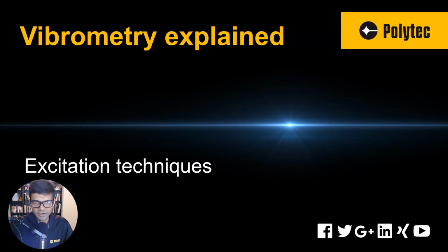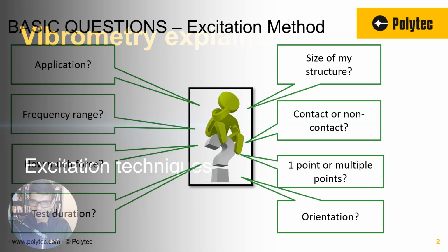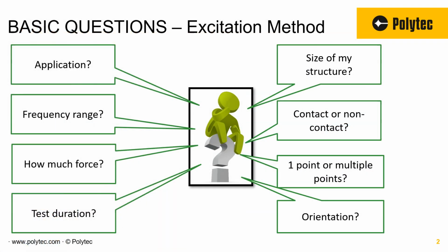All right, let's talk excitation methods or techniques today. Anybody who's doing any kind of vibration analysis, modal analysis, is going to get into this question sooner or later. So I want to start with, before I show the different methods, some of the questions you want to ask yourself as you select the excitation method. How much force, frequency range, the size of your structure, test duration, all this.